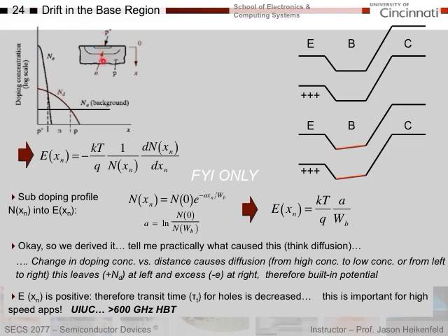And so the current flow would be in this direction. You can see that these are diffused in, and so here's my background concentration for the wafer. I diffused in my phosphorus with high temperature, and I diffused in boron here with high temperature to make my P+ region. So I get P+, N, and P whenever the doping levels exceed the previous doping level.